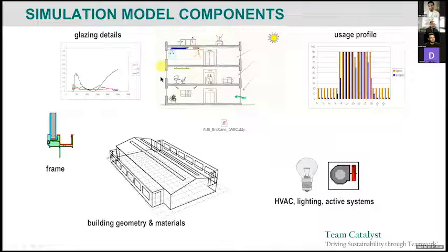Then there's a series of internal loads that most air conditioning engineers are interested in. That has to do with solar radiation through the windows, or internal heat generation due to lights and people and occupants. And then we talk about ventilation, that which you put in and you want, and that which leaks because of the quality of construction of your building.